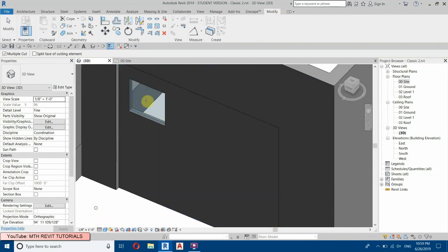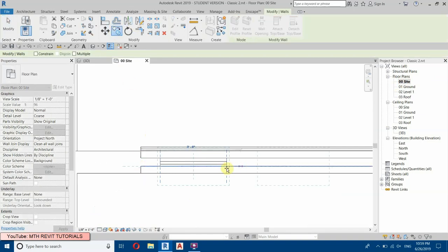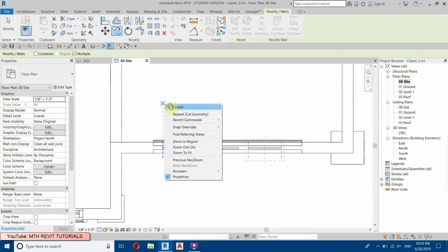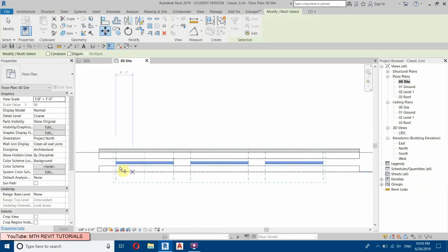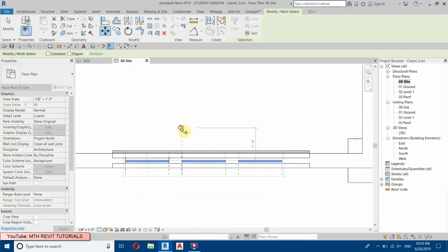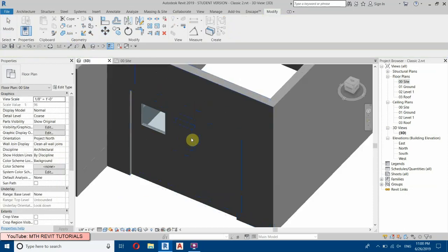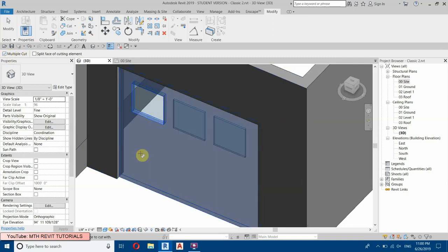And now I will just copy this one, so let's go to site plan, select this and copy. I will add 2 more. Okay, select, just keep this checked. Let's take this to the center, select all these 3, then just take that to the center like this. Okay, we need to cut these 2 also. So select cut geometry, just check this multiple cut, then select this wall, then these 2 curtain walls.